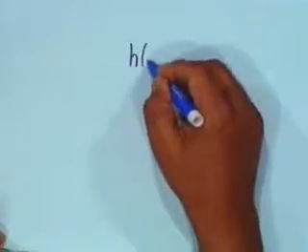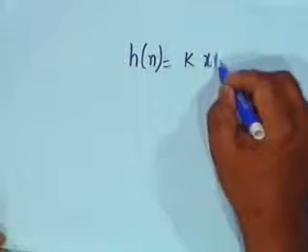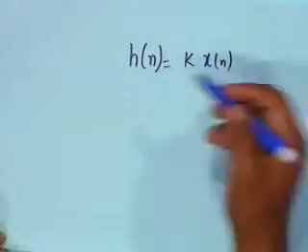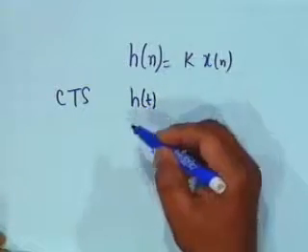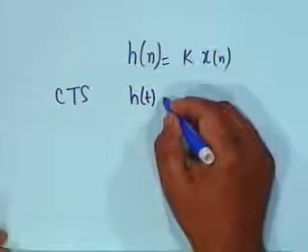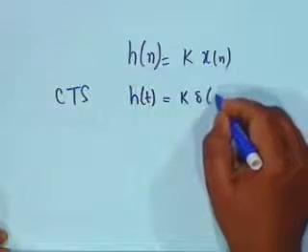You give me the example of the diode circuit. We shall examine this and show that it must have memory. Otherwise, it cannot be so. That is for zero input. A capacitor, for example, even if the input is 0, it can store some charge. And therefore, it has memory. A memoryless system has to have an impulse response h of n equal to k x of n. In a similar manner, in the continuous time system, CTS, the impulse response, by exactly the same argument, for a memoryless system must be of the form k delta t.